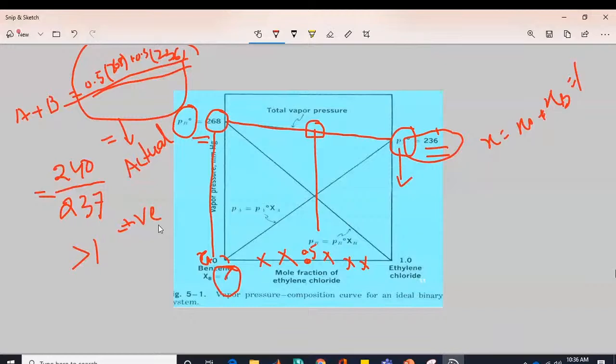Now, if we talk about the principle, when a hot mixture is allowed to enter from a high pressure zone into a low pressure zone, the entire liquid mixture is suddenly vaporized. The process is known as flash distillation, vaporization. During the process, the chamber gets cooled. The individual vapor phase molecules of the high boiling fraction get condensed, while the low boiling fraction remains as a vapor.